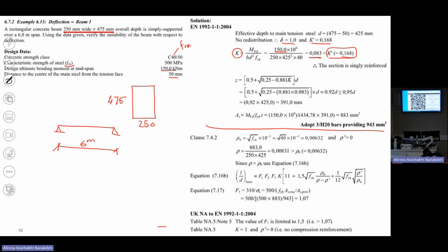And for each of those cases, we had different formulas. This was the main topic we talked about from the beginning of this semester until you went to the construction area, right? We had a lot of examples of singly and doubly reinforced sections. So this was the criteria we use to distinguish if we need to go for single reinforcement or double reinforcement. You do that at the beginning. The MED is given, it's here, 150 kilonewton meter. That's the external force coming from ETABS, okay?